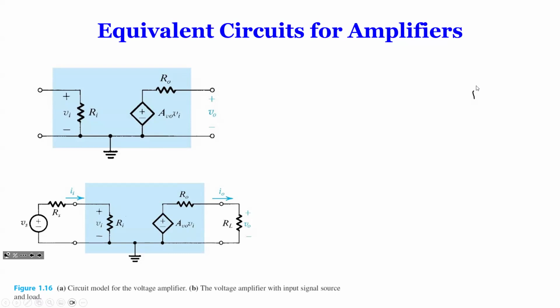So now let's look at the output. Why is it important? Let's say your load resistance is 10 kilo, like it's very typical in our examples in the future. And you have an output resistance, which we can call internal impedance, RO, output. So if this is 10K, and your output resistance is, let's say, 10 ohm, what happens now? This drops very little voltage. Most of the voltage over here is applied here.